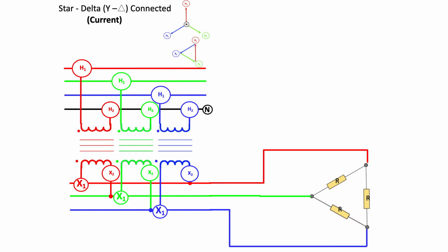I've also drawn in the voltage phasors in miniature up near the title there, just so we can keep track of them. Now, I've adopted the same standard pretty much that I did with the voltages, but keep in mind now we're looking at currents. So all the currents that are associated with what we're going to look at on the primary side, I'm going to use capital letters or uppercase letters. And on the secondary side, I will be using the lowercase letters.